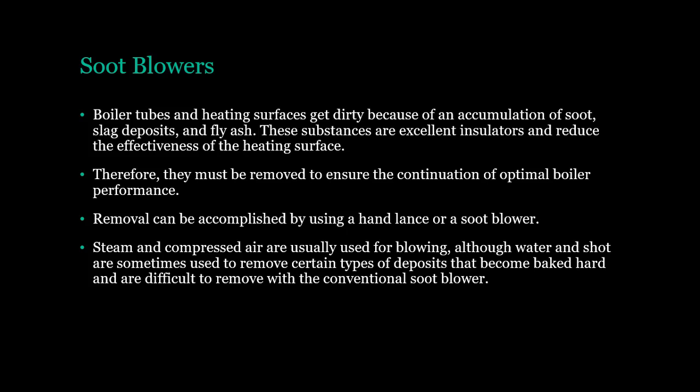Removal can be accomplished by using a hand lance or a soot blower. Steam and compressed air are usually used for blowing, although water and shot are sometimes used to remove certain types of deposits that become baked hard and are difficult to remove with the conventional soot blower.